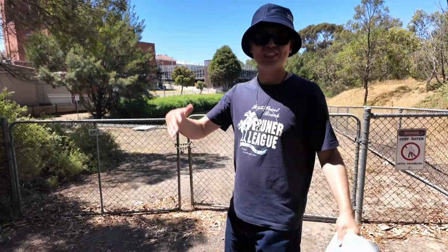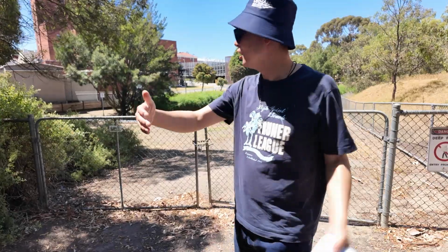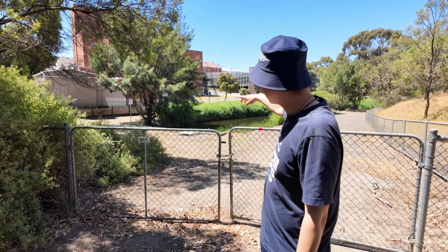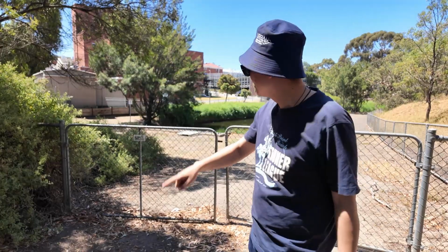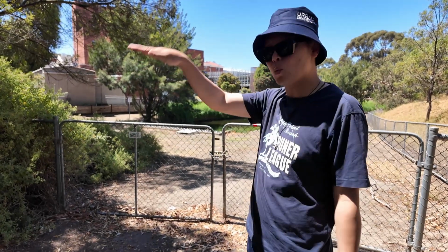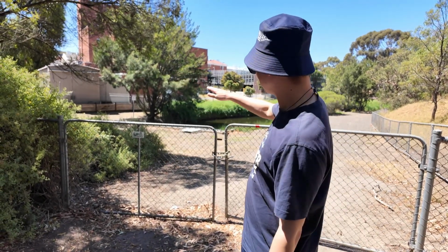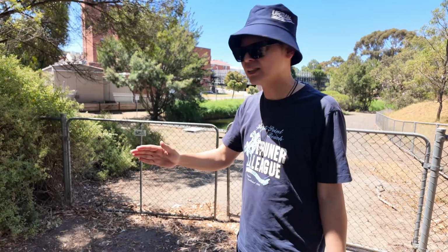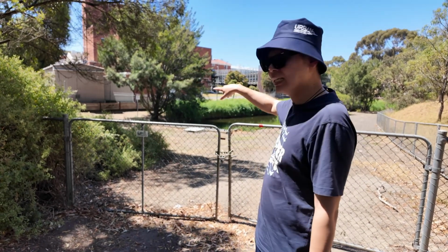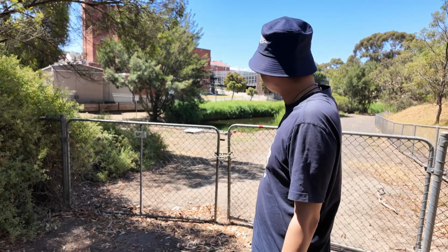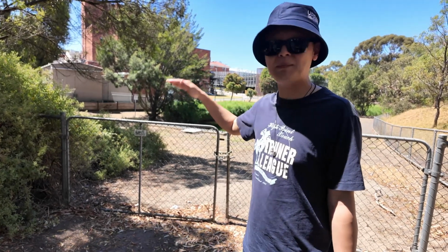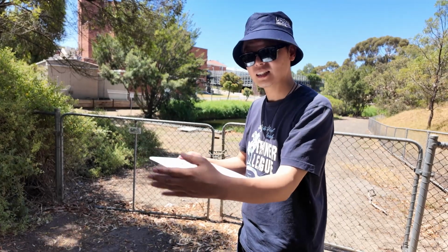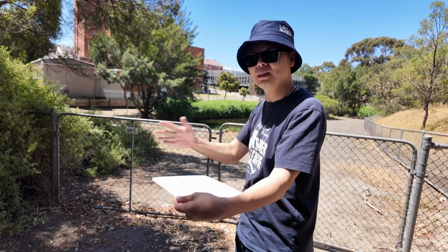Okay, so I'm taking everyone to the diversion point. So this is where the water has been diverted from this creek to the wetland. From this point, from the weir level to the wetland, is about a 2-meter drop. Okay, so everything is done by gravity. Because it's an online diversion, this is essentially also a sedimentation basin. Right? Because we have a weir to stop the water, and this part becomes a sediment basin.